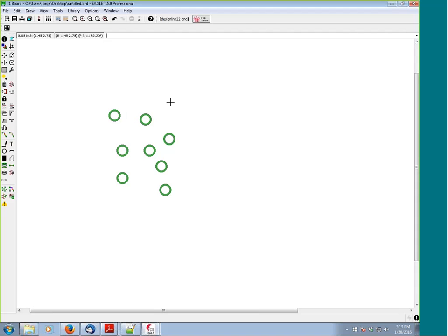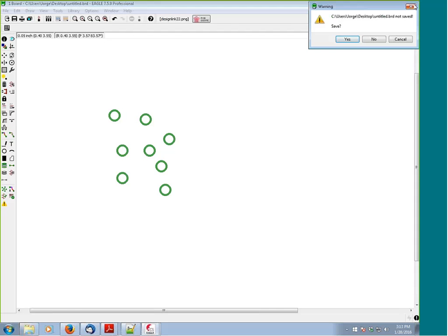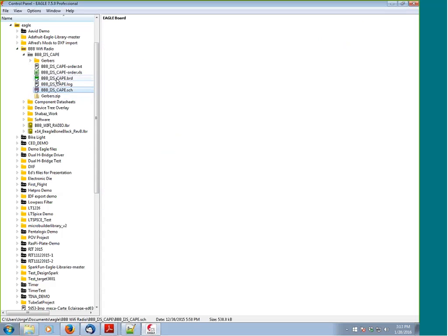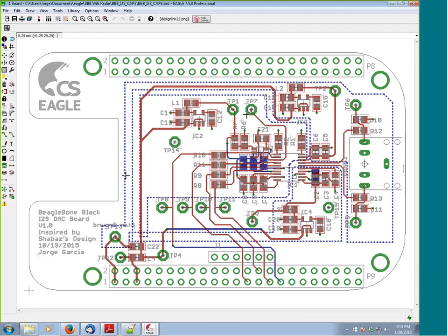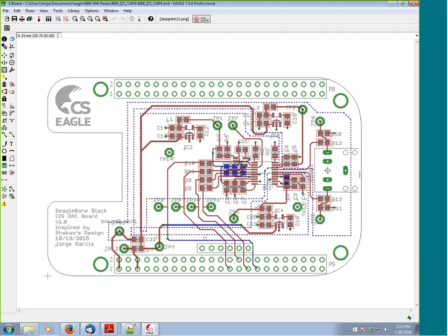In my application, what I had going is slightly different because I have an audio DAC board that's receiving digital signals coming in, and it has to output analog signals. What you want to avoid there is any noise coming from the digital side. I'm going to open it again because I didn't discuss very well how it ended up working. With the audio DAC board, the I2S stream that's coming in is at 24 or 25.476 megahertz, with sharp edges. At every transition, it's creating noise. It's pumping noise into the circuit.